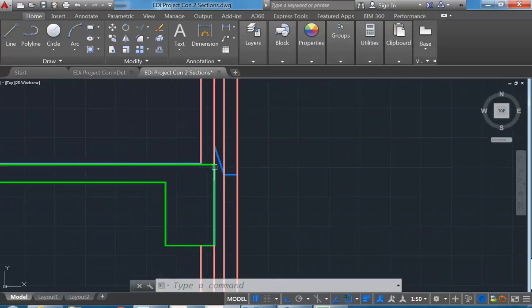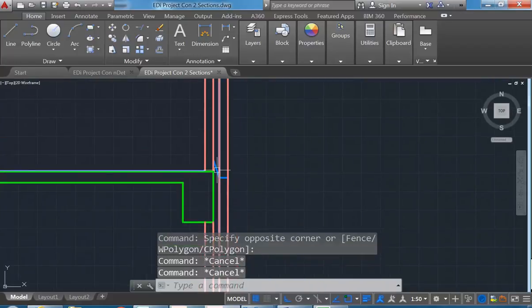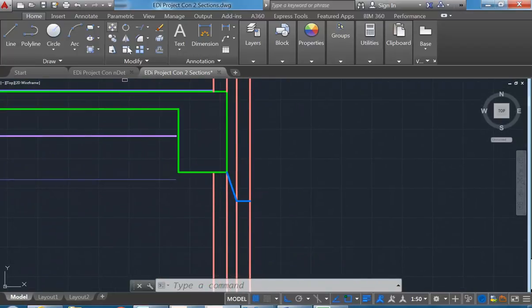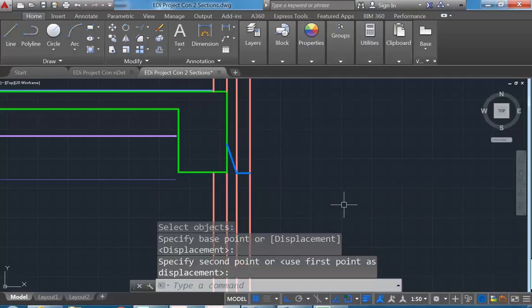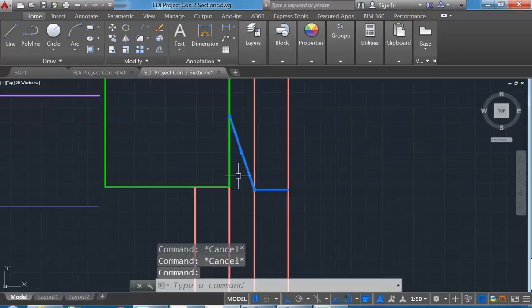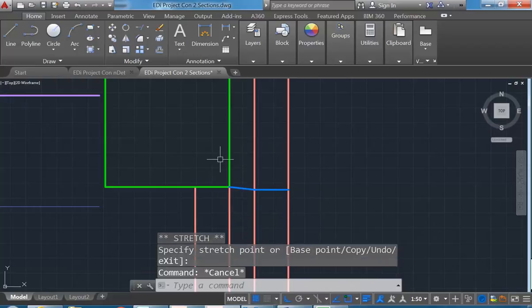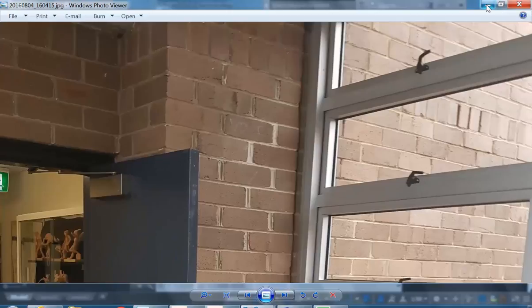Okay, so it's different on that level. On this level, it's actually at the... oh, that's right. That's okay. That's exactly how it is on that level. But on the level above, it's well, sorry, no, that's not right. So it's up at about that height. And probably, actually, it doesn't slope very much. It's just an unusual detail, that one. But it makes sense because it's really to make sure that it's draining from the edge of the beam. So that's why they've got those weep holes there.